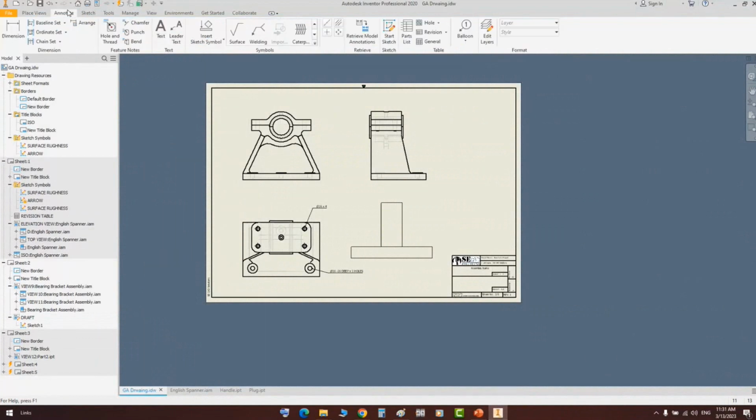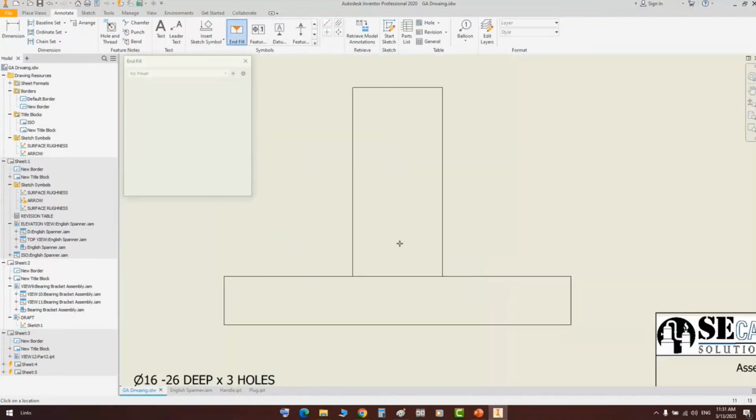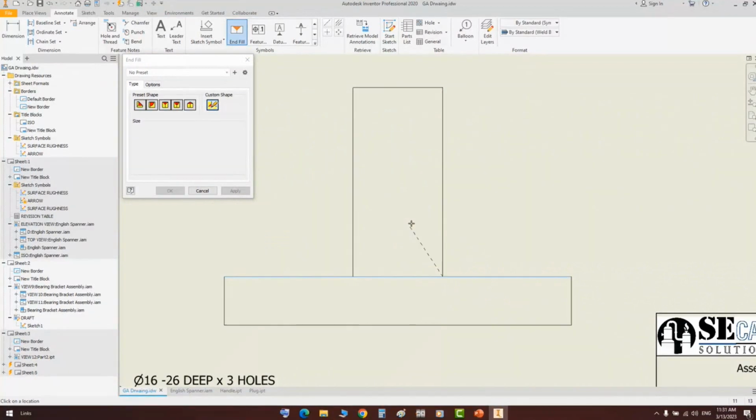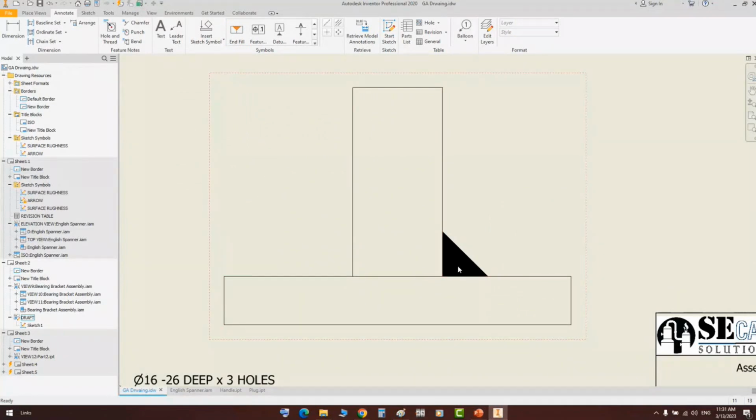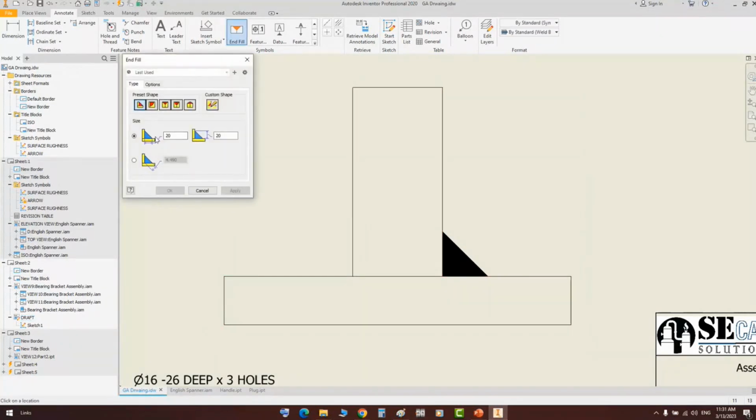Let's click finish. Now if you would like to add a weld sample, you can select this line and select the configuration of the samples that you would like to import. For example, we need to make a fillet weld with values, let's take 25, and select the corner here. So automatically you get an option to insert this fillet weld like that. Again, if you would like to make another fillet weld with different values, like 20 by 10, directly when you make it like that, you can flip the value.